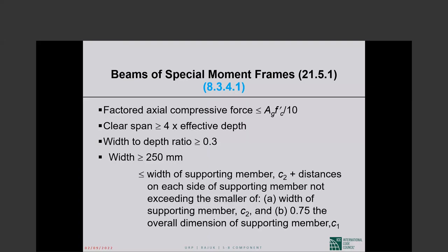Where does the moment capacity come from? The effective depth is very shallow. So I do not exactly know what you are thinking of. No, there is no explicit lower limit on the depth, but if you ask me, it has to be a good faith beam, not something you are trying to manipulate your way into.